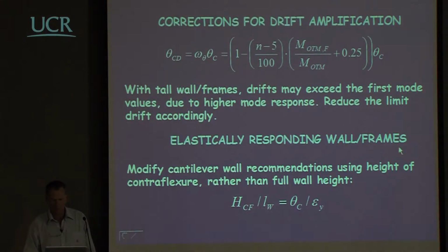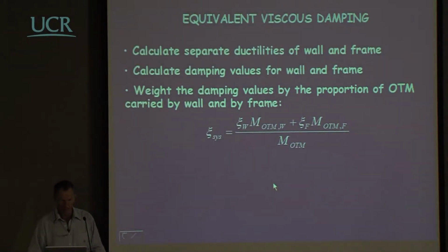Elastically responding wall frames, well, we've talked in cantilever walls, in bridges, and in frames that structures, particularly in regions of moderate seismicity, may respond elastically, and again, modifications and suggestions are made here for combined wall frames, but they're essentially the same as for walls, and we need to make no further consideration of them.